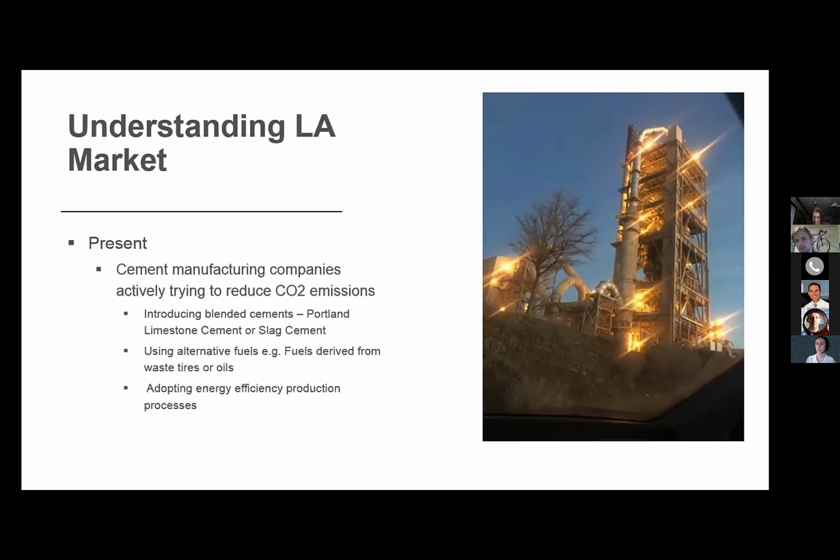So by itself, limestone cement doesn't perform as well as straight cement. I mean, you've got 13% less sintered material in there. But sometimes people need a low water cement ratio for durability concerns or permeability issues. So strength may not be an issue, you just want the low permeability for maybe sulfate conditions or something like that.